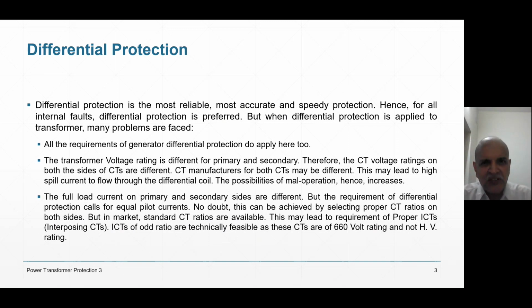What I mean by that is this, that if there is an internal fault, the relay does not operate. I mean, in very rare cases, but it does not operate. And for external fault, it operates, which should not be the case. And that happens. And the solution to that problem may be rare, maybe 1%, 2%, but it has not been found out. So differential protection is a very complex protection. But to start with, 98%, the differential protection is most reliable, right?